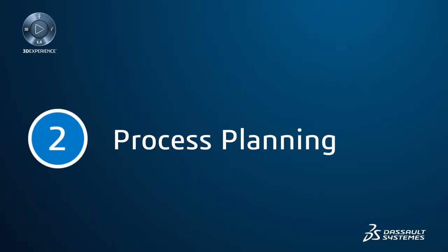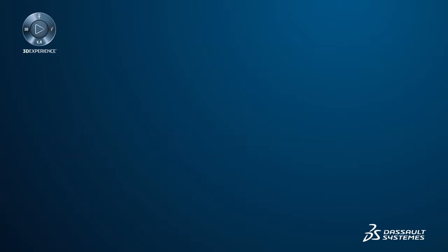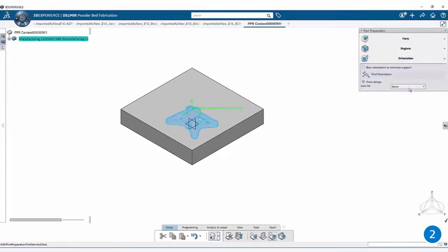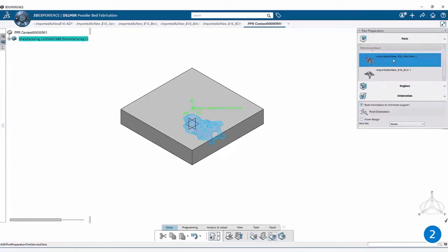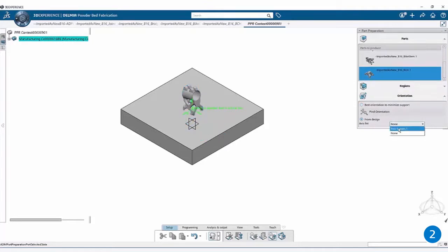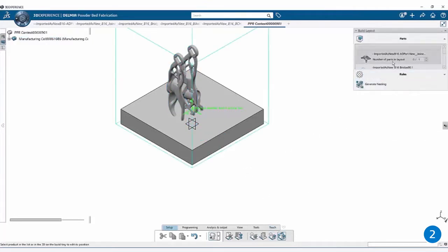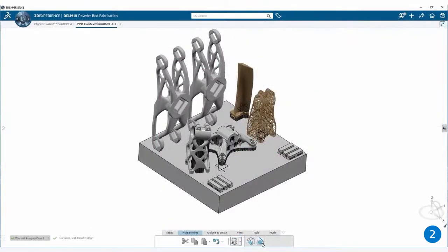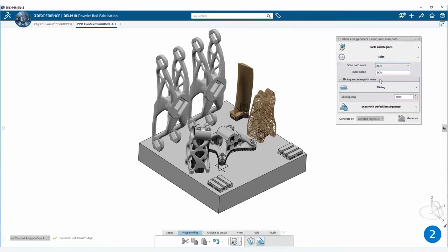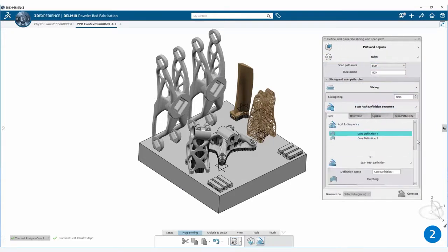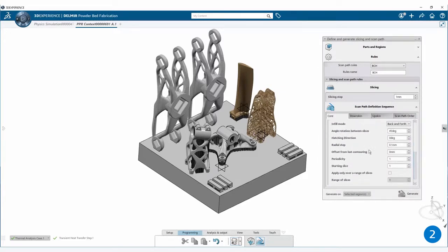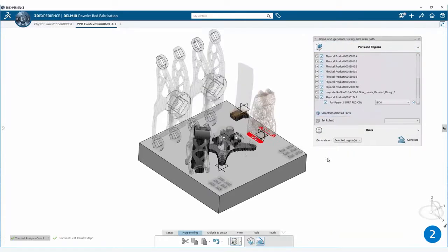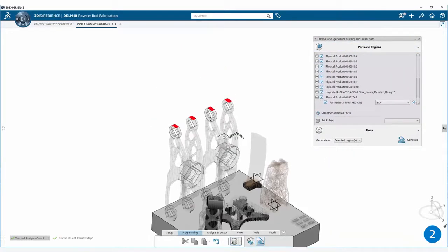The additive manufacturing fabrication applications allow you to design and plan out any additive process. For your machine of choice, you can create a build volume and build plate, automatically nest parts to maximize build volume usage and minimize supports, set custom rules for slicing, scan patterns, and process parameters for the entire build or for individual parts. Finally, visualize the scan path for diagnostic checks.